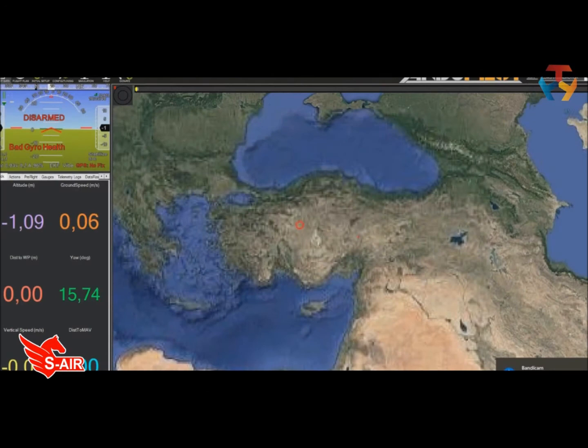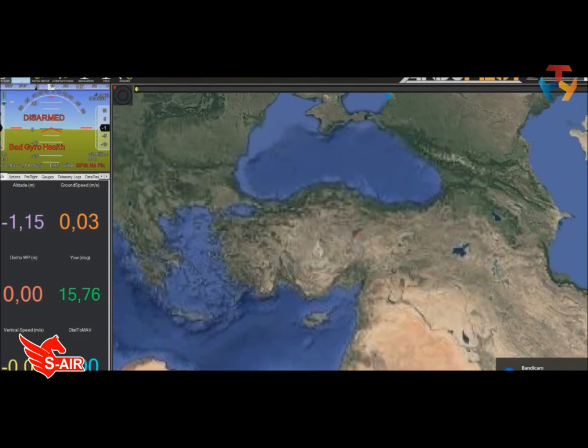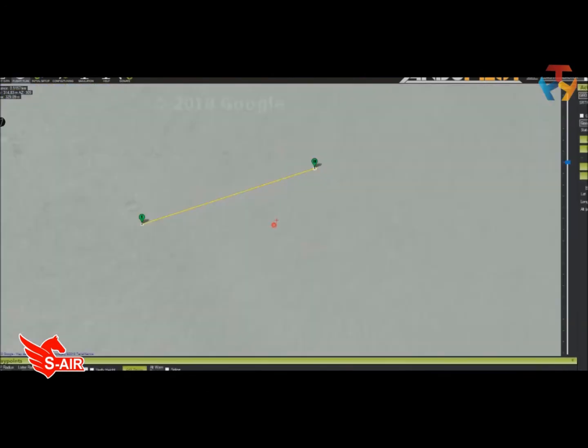The SAR team found the chance to experience different autonomous flight cards such as APM and Pixhawk. APM is not preferred because of the lack of a GPS unit and lack of perfection in flight. That is why Pixhawk as the flight card is chosen. The reason ArduPilot is preferred as a software library for autonomous flight is that it is the most preferred open source software library for autonomous flight because it offers many useful features.